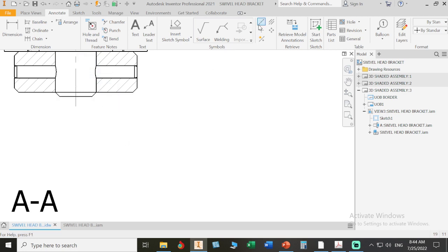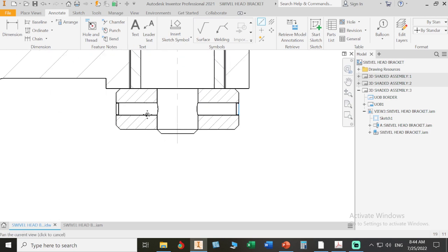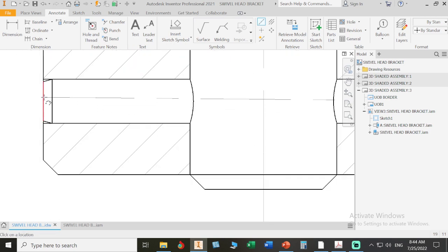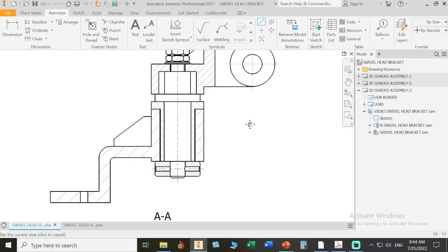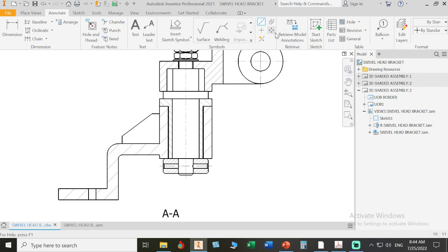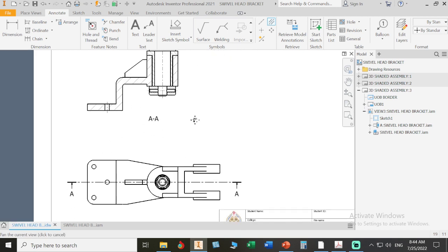And also I have from here, the end of my pin to the end, to the mid, sorry, from the mid to the mid. And this is the other center line. You can add a center line bisector here, by clicking these 2, and continue adding all center lines that it needs. Save.